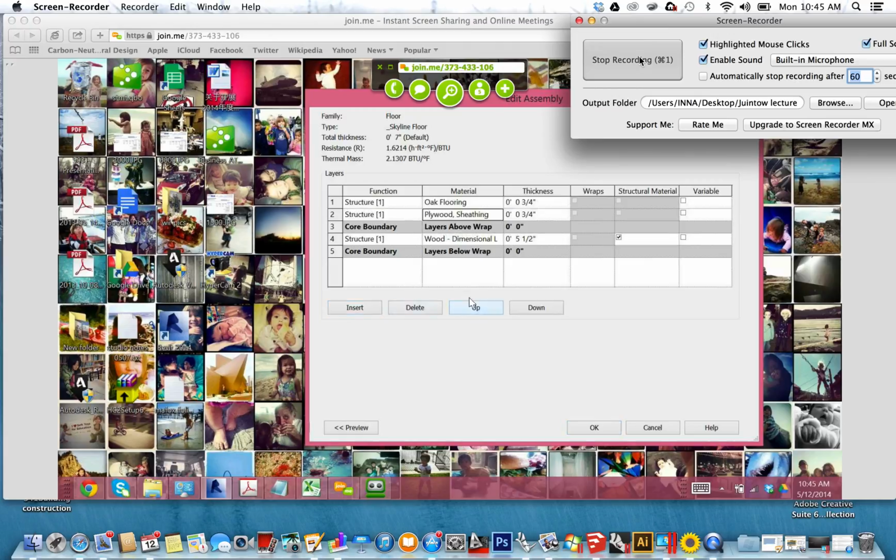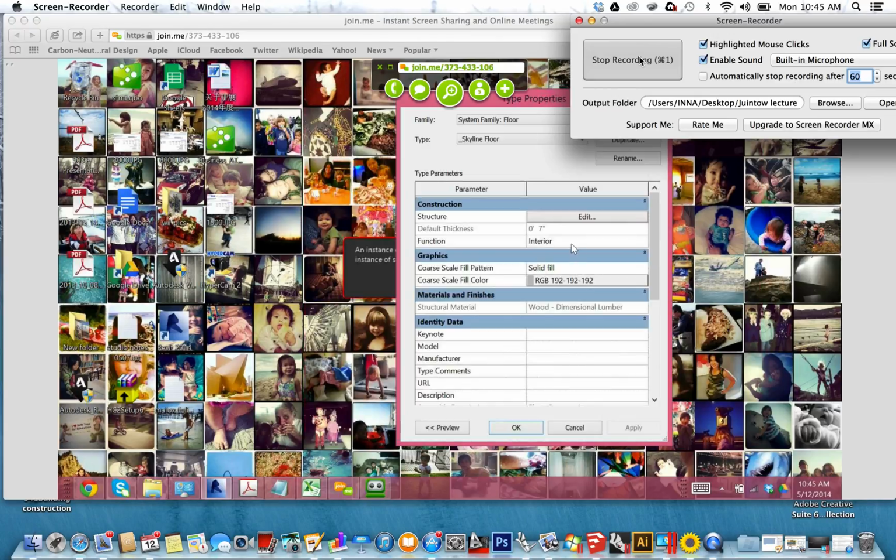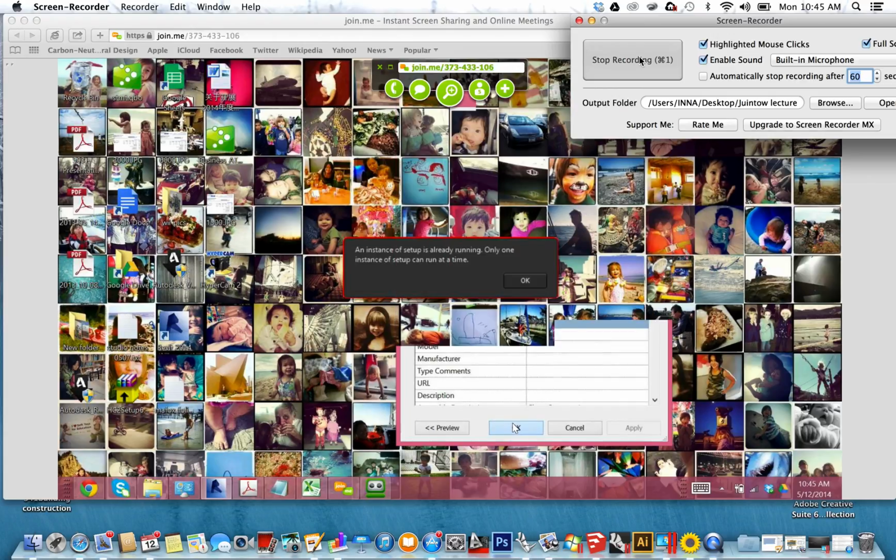So I'm going to move the plywood and the flooring above, because we may change it to just plywood, so let's keep that the finish. Do you guys know there's a difference with the structure? When the guys or gals in the field go to lay stuff out, there's no finish there, so they want the dimensions to the structure, so you can put the joist where it goes and the stud where it goes. Otherwise, if you give them a weird dimension like 5/8, so the point is you want round numbers to the structure because the finish doesn't exist. So we're going to hit OK.